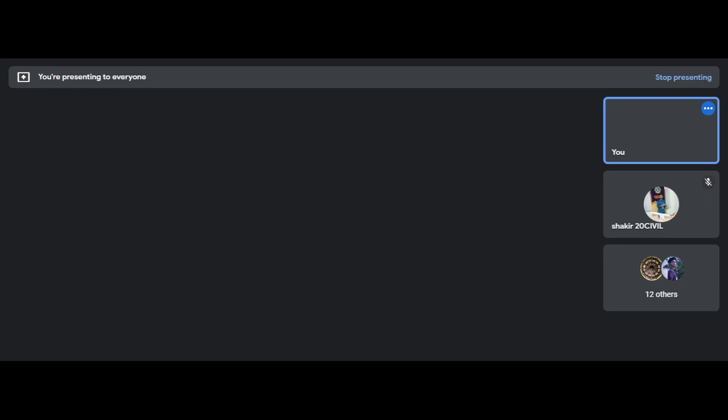Students can refer to first week, lecture 5. We would want to drain as much as possible by gravity because it is cheap. You don't need to set up a pumping system. In case you are not able to drain by gravity, if the landfill layer does not have enough slope, then we go for pumping. So both the gravity method and the pumping method are used to remove the leachate.